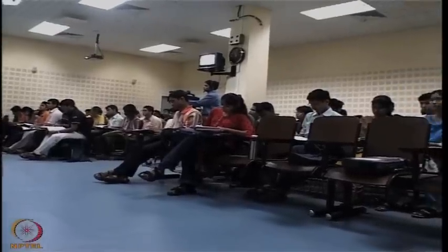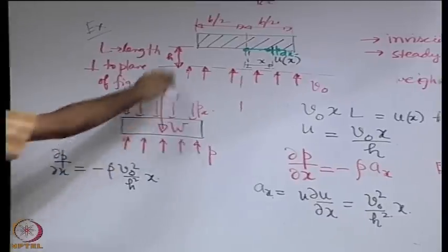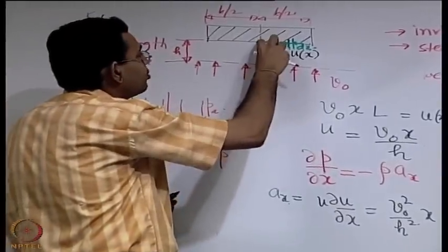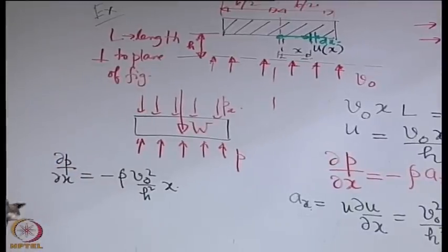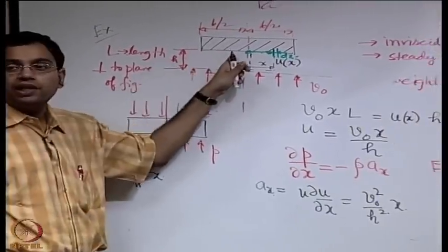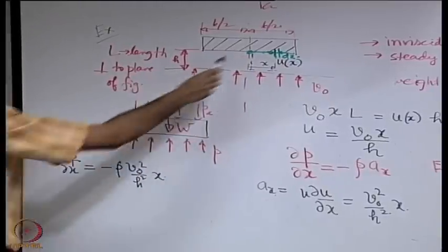and we are interested to find out what is the pressure on this strip. So if we integrate along this, we are integrating keeping y equal to h, which is a constant. So the other component of velocity has no effect because of no penetration, v is 0 here. So we can integrate along this surface.